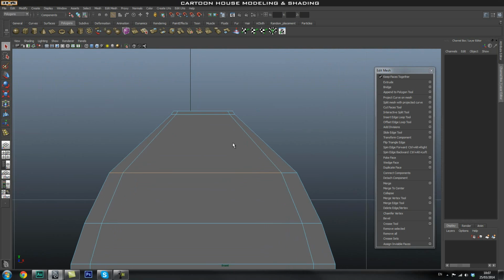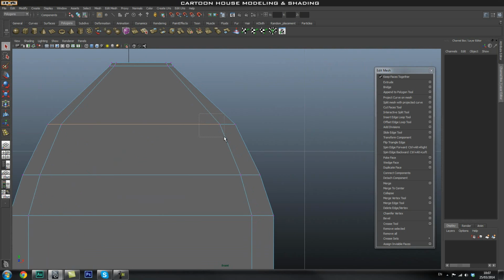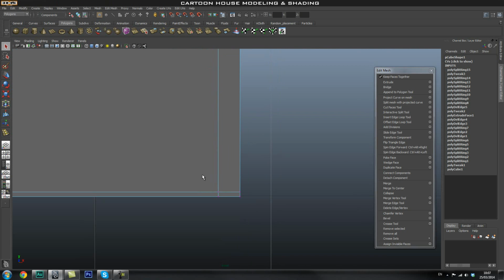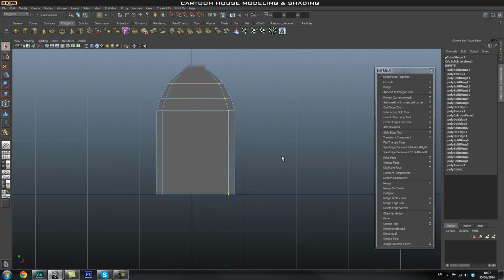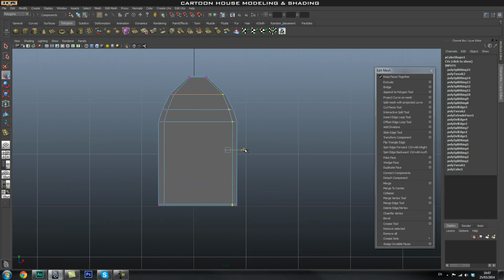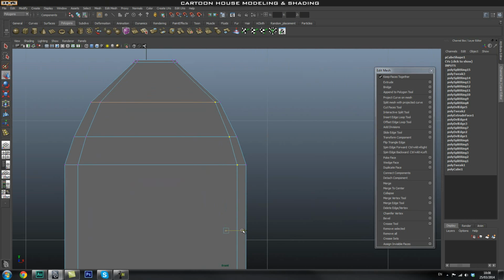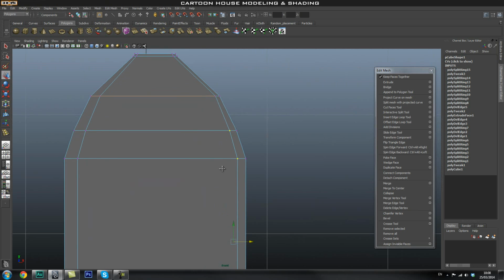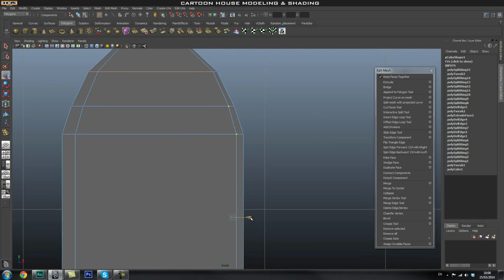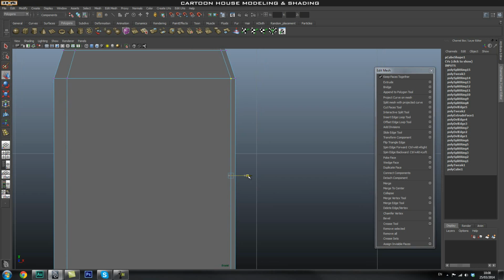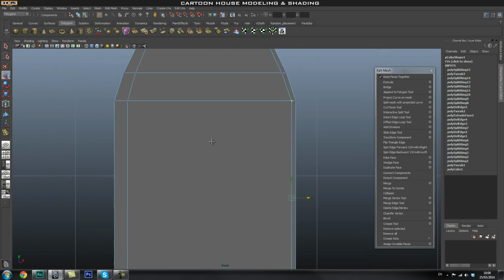And we're going to select the vertices that we want to move. So I'm shift dragging those vertices. And there as well. Okay, and these guys. I can press V on my keyboard to start moving these guys around. And now what I'm paying attention to is this top edge. Okay, once that guy's at the right place, I'm going to shift, deselect. Okay, and then I'm going to make sure that this guy's at the right place. Once it is, shift, drag around it to deselect it, and then move this guy as well. Okay, so now that looks really good.